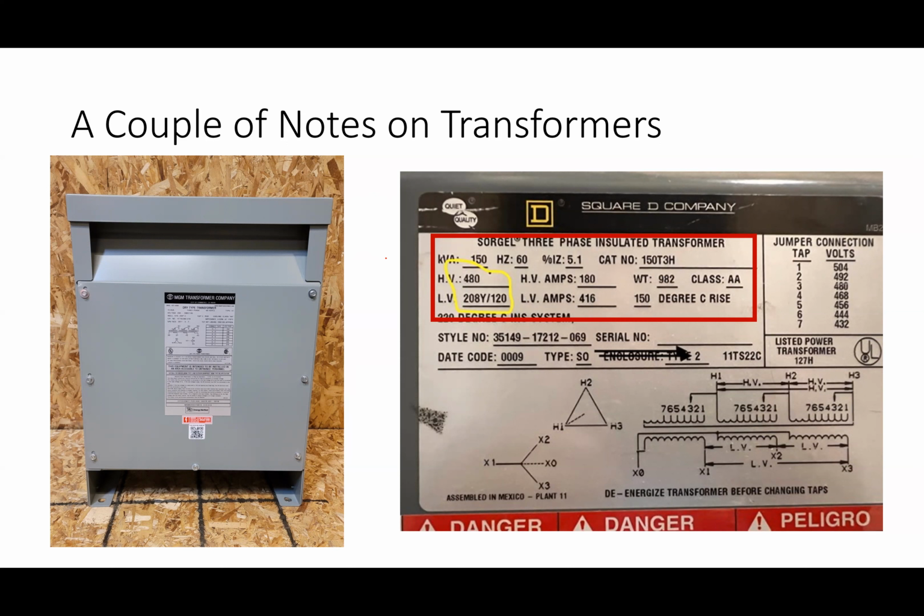Well, a Faraday cage is basically to block fields. It's for interference protection, but it's a similar kind of concept. So I said you induce currents inside the core. You also said if I put a voltage on the coils, and that creates a flux inside the core, we had those little magnetic atoms, basically dipoles, moving around inside of that thing. So if I touch that core, it's hot.